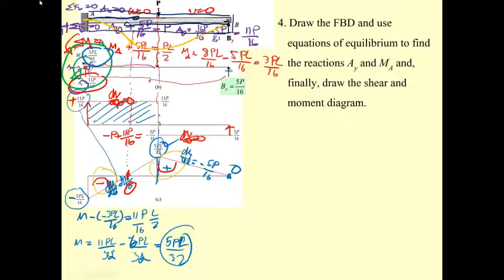Normally this beam has its own reinforcement already. Just put this one like this, and this one going like this. You also may put some reinforcement for the shear stirrup.